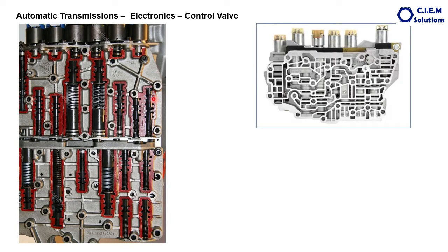Depending upon various factors, the control valve used to modulate or synchronize the oil flow based on many inputs taken from the driving vehicle, and supplies the oil to various components like clutches and some other valves for the smooth shifting of the gears. Now the movement of these spools is taken care of by electric components called solenoids, also called the transmission solenoids.